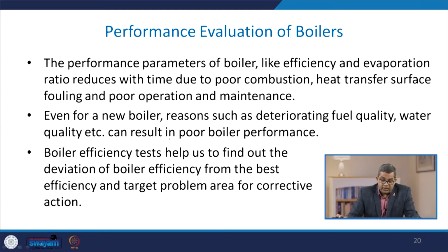The routine evaluation of boiler performance is a very important phenomenon, because this diagnosis gives you an idea whether your boiler is functioning well or there is some malfunctioning, or something goes wrong within the boiler system. So, the performance parameters must be analyzed first, that is, under what category and what parameters we would like to evaluate the boilers. The performance parameters of the boiler are efficiency and evaporation ratio.